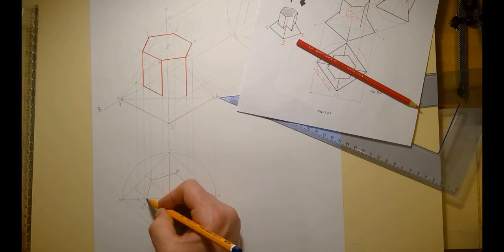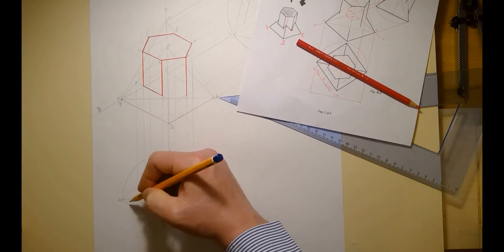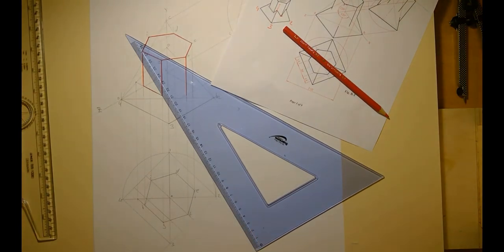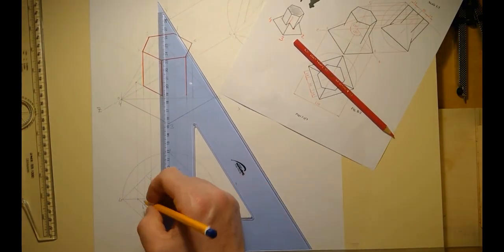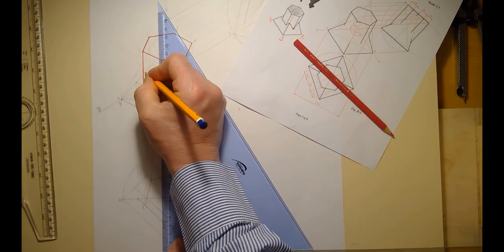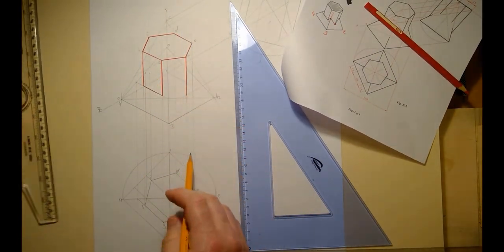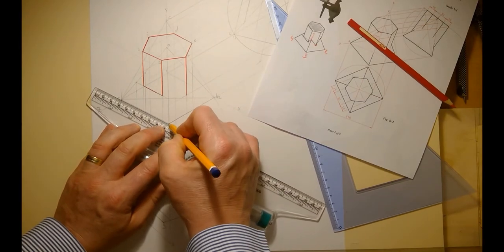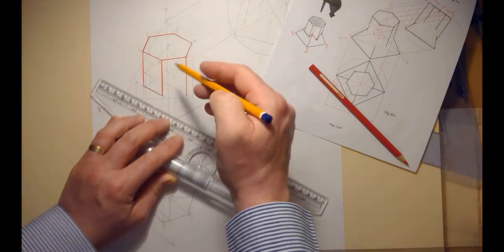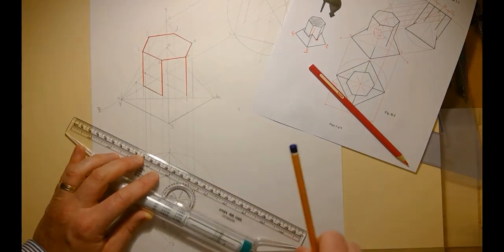But when I have this point here, I can bring that up to the edge 40, and again bring a line parallel to my lines that I have here already. So I'll bring up that point up to my edge 40. So that's on my edge 40 now here. Okay, and now I can transfer that line across parallel. And where that cuts through my edge 30, that is the point that I'm looking for.